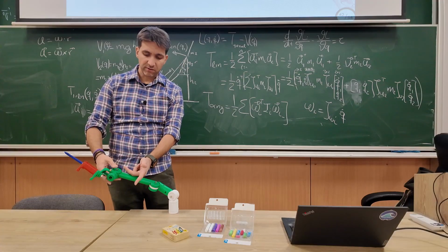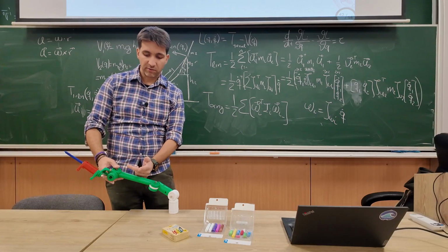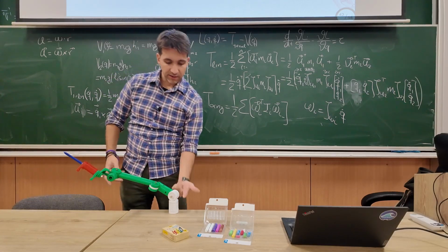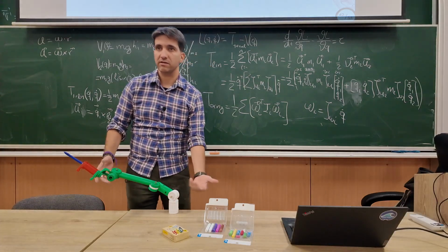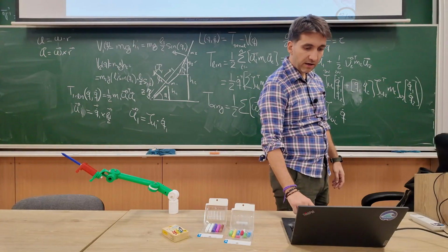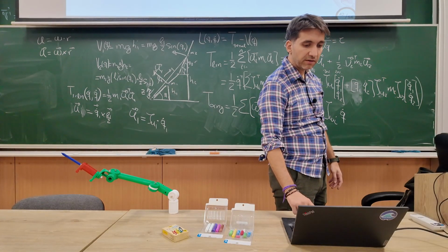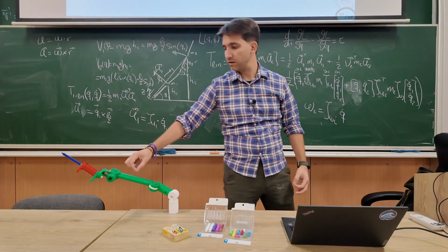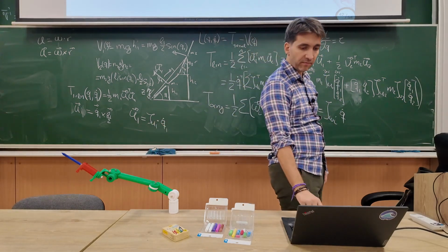So the moments of inertia will tell me that this thing has some inertia when it rotates around this axis, but I care how it is around this axis, basically. And this thing, again, we know how to calculate from forward kinematics. I do the forward kinematics until that link, I know the orientation, and that's it.